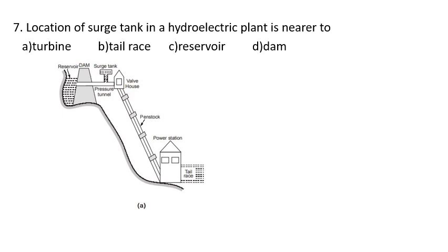Dam, which helps to store the water and prevent the flow of water, and it will be a concrete structure, a strong structure which will protect the water at the reservoir. From the reservoir a pressure channel comes from the dam which will carry the water from the reservoir and directly enter the valve house, and from the valve house the penstock starts and reaches the power station.